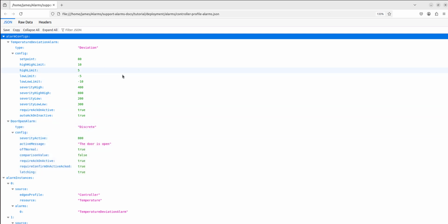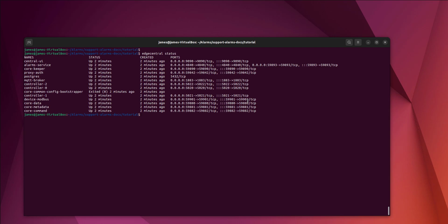And you can see some of the details that can be modeled here, including standard set point levels and the specific values that warrant the different alarm levels. We can monitor high limit alarms, low limit alarms, and even things like high alarms, which represent critical alarms in the rich standard alarms model we're using. The attributes shown here are only a subset of what can be modeled. It really is a rich specification.